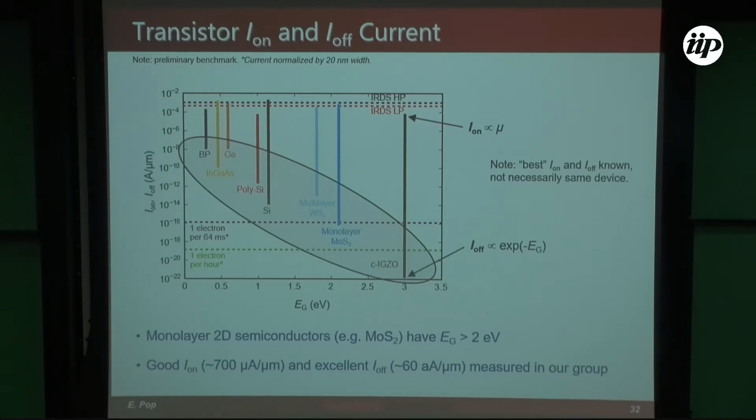So, if you have good mobility and good contact resistance, you're going to get the on current that the low power and high performance metrics require, right? And you can see that silicon obviously meets that metric, but germanium and indium gallium arsenide surely meet that metric. Indium gallium arsenide meets it very well. And MoS2 just barely maybe meets the low power metric.